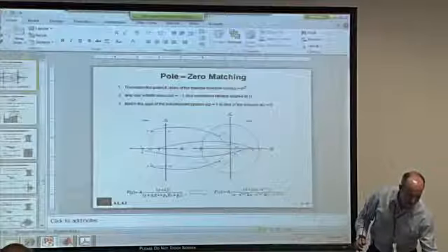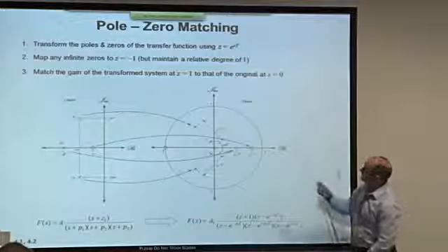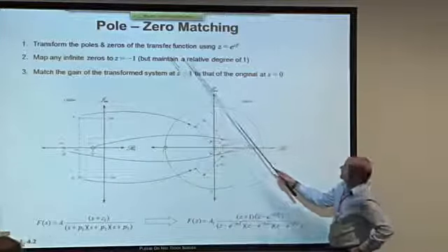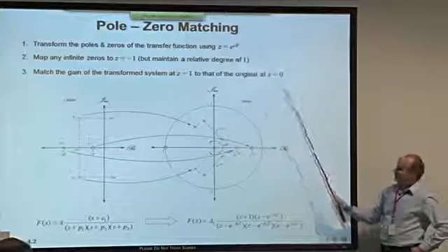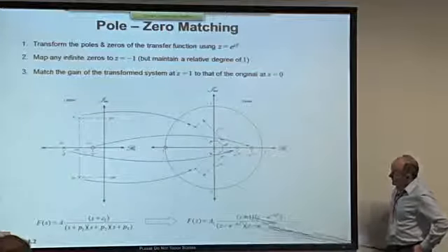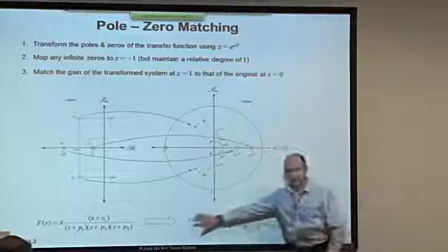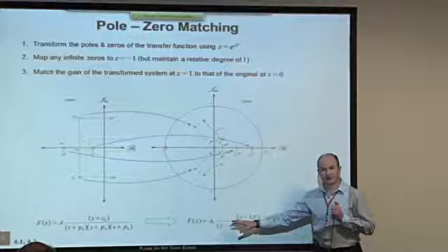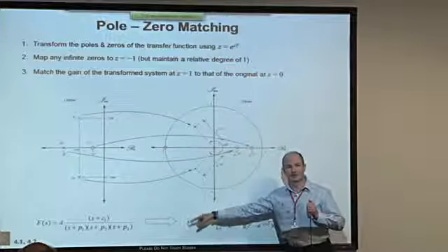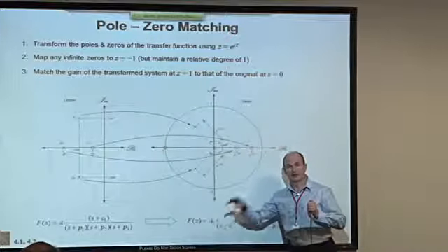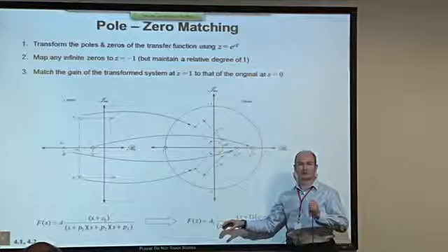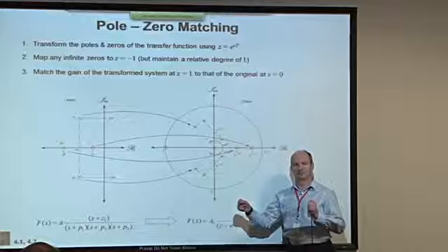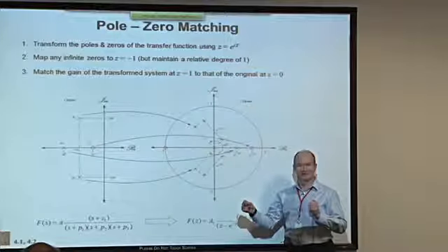Now the significance of step 2 is that when we go back to the 2-pole 2-zero controller, when we've got a relative degree of 1, the form of this, when we construct the difference equation, means that u of k will not involve a term involving e of k. The newest value of input won't be a term in the newest value of output. It'll only be delayed values of inputs that have an influence. So we're waiting one sample period before we compute the output.